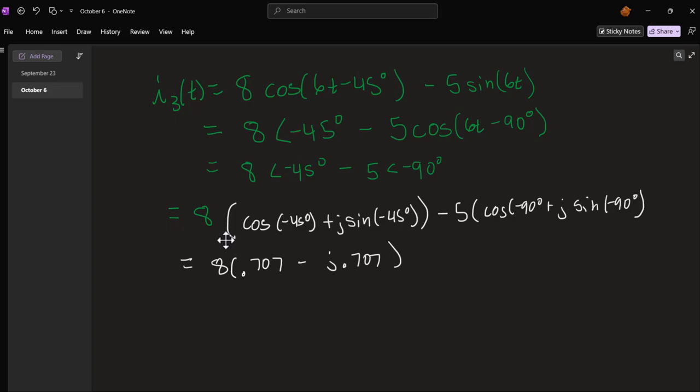So usually for the capacitance, we'll do minus j over ωC. And that also lets you see that it is negative imaginary, whereas the inductance is positive imaginary. And then once you do this, you can treat inductors and capacitors just like resistors. So you can add them in parallel and in series and all of that.